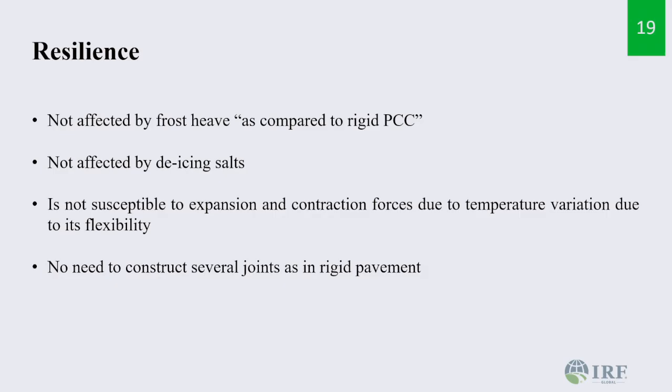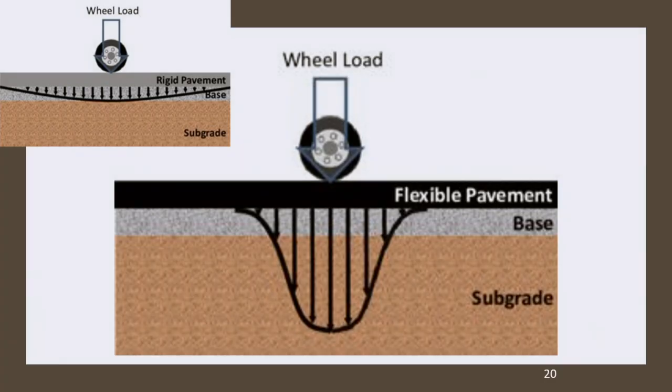But if you use it with rigid pavement, especially if you use rebars for temperature or shrinkage compensation, then you get a big problem. Also in asphalt, the need for construction joints is not there as in rigid, because of, again, flexibility and the ability to sustain lateral movement.